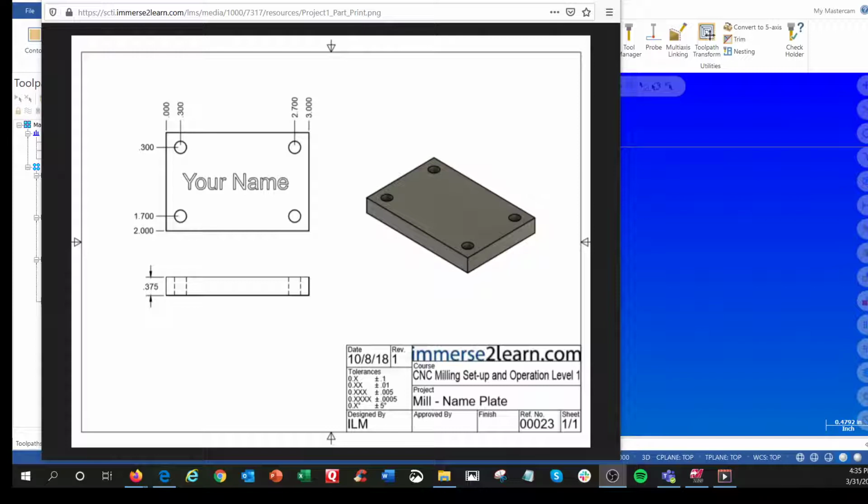So if we're looking at this simple rectangular part, and we're trying to machine the outside and the holes, you need to plan your process. If you want to be like production, make 100 of these, unless you buy the material exactly that size, you're going to have to machine the rectangle, which means you need to hold it. And you're going to need thicker than this 375 material over here.